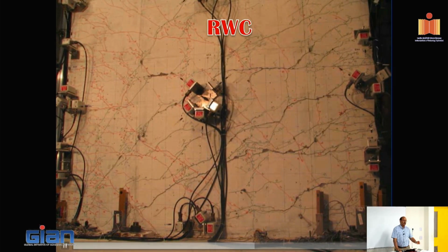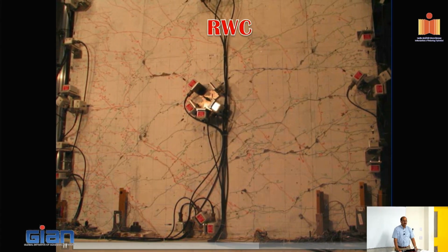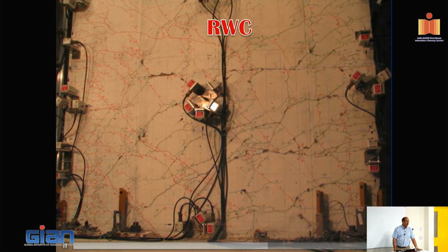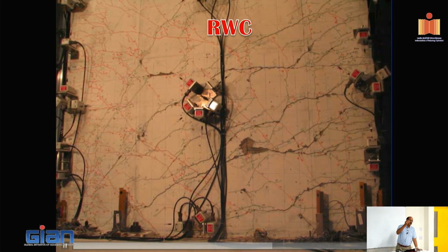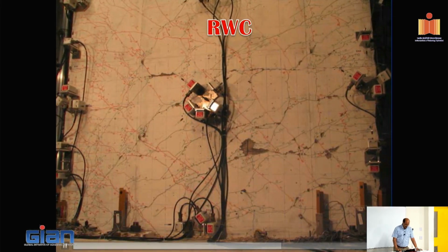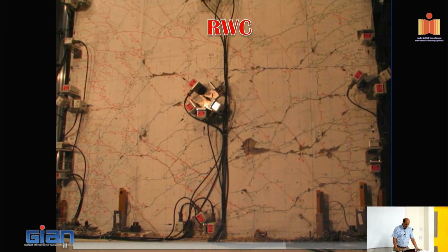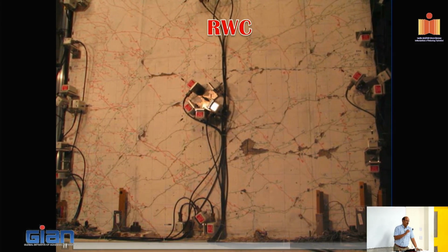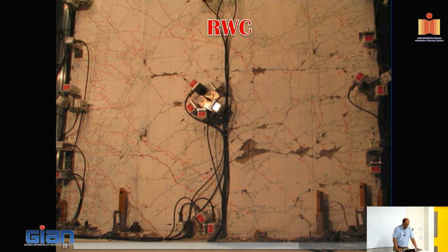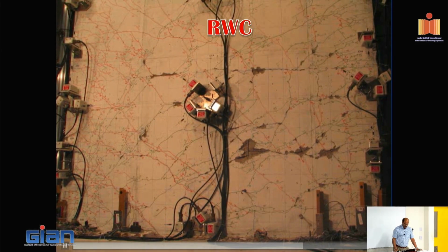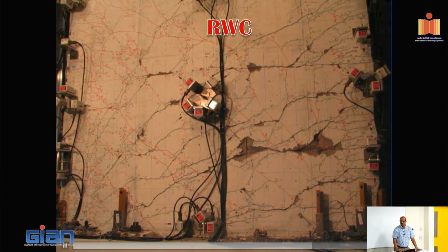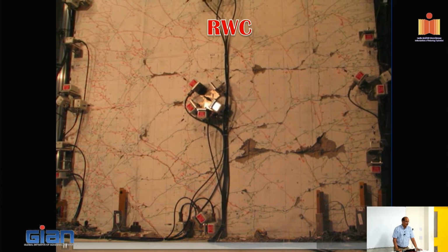So anytime the force resistance drops by 20%, we typically consider that to be a failed structure. So in this case, because of the hardening, you are continuing to increase the resistance, but I want you to pay attention to the damage that takes place. So plastic action causes some damage, they are controlled damage, nonetheless it's damage. So after an earthquake, typically you don't repair plastic hinge because it's not easy or cost effective. They tend to take the structure down.